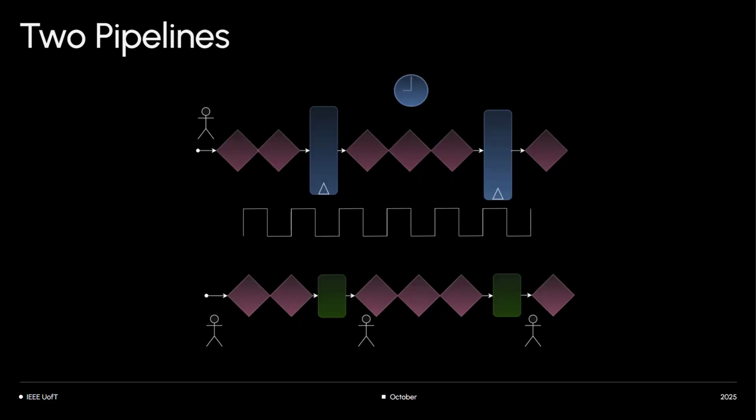If you take an AND gate, or any gate, and you flick its input, how much time will it take before the output responds to the input flick? That's the propagation delay. Pretty much how much time an event takes to propagate from the input of the gate to the output. Fatter gates take a longer time to propagate an input. When I say fatter gates, I mean gates on the old nodes, like 120 nanometers, 180 nanometers. The fatter the feature size, the slower it is, and that's why people are mad about trying to get smaller and smaller transistors.